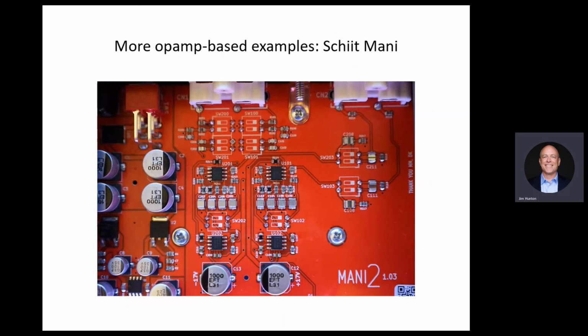It starts with 16 volts AC, generates internally 10 volts, and splits that internally into plus minus 5 volts. It's all linear. So it's taking advantage of op-amps that work at plus minus 5 volts. That's newer generation op-amps. Not necessarily the best approach.